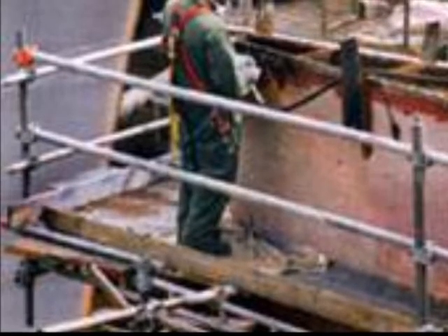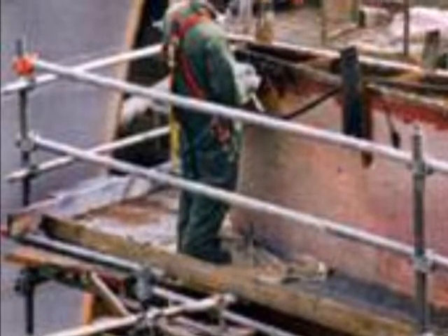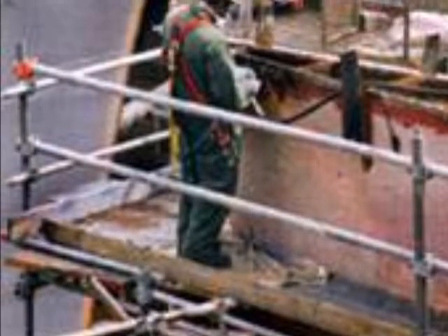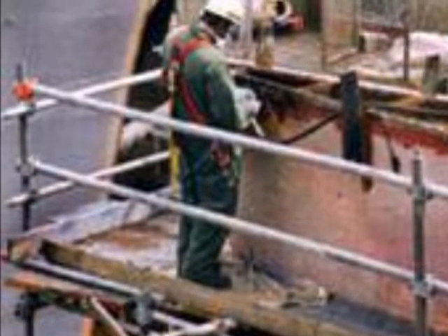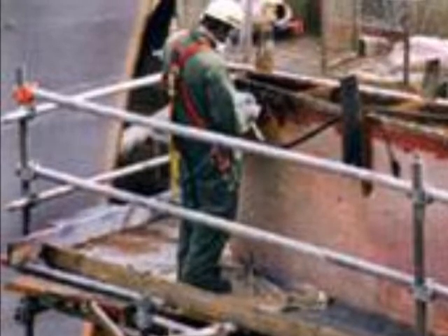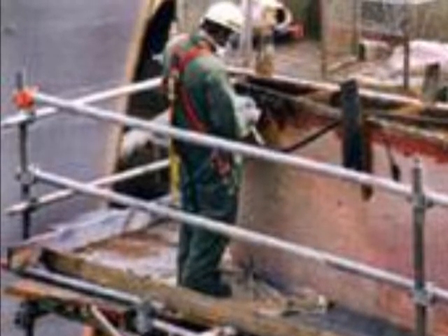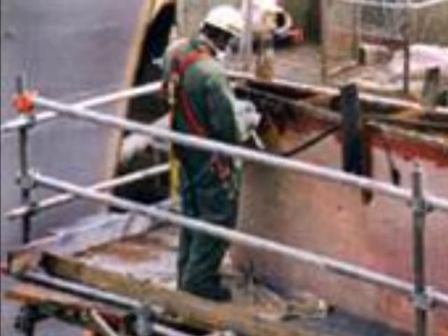To prevent falls on scaffolding, guardrails must be installed along open sides and ends. The top rail of the guardrail must be somewhere from 38 to 45 inches tall and withstand a pressure of 200 pounds. Mid rails must be halfway between the top rail and the platform. The scaffold must also have a toe board that is at least 3.5 inches high.